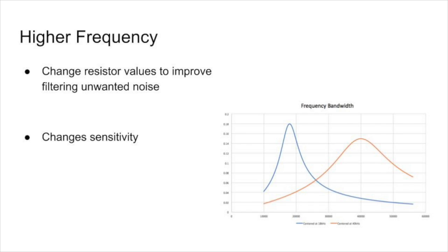We believe that if we increase the frequency the transmitter sends out, the receiver will be able to have better readings. Since we are using a schematic that uses a dual element transducer, we are going to find a different type of dual element transducer that would perform better than the one we have. We then change the resistor values of the board to change the sensitivity of the receiver.